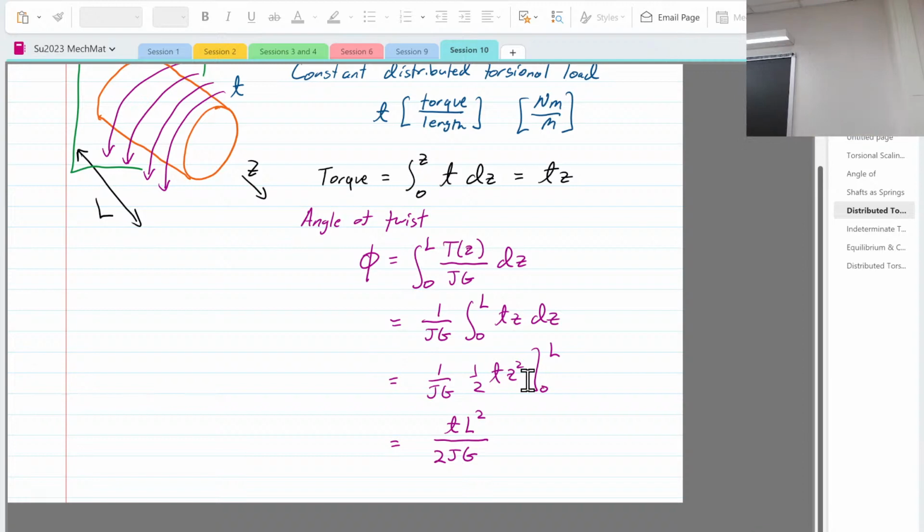So it's density times gravity times length squared divided by 2 times the elastic modulus. I did out the units: density in kg per meters cubed, gravity in meters per second squared, times meters, divided by meters squared.